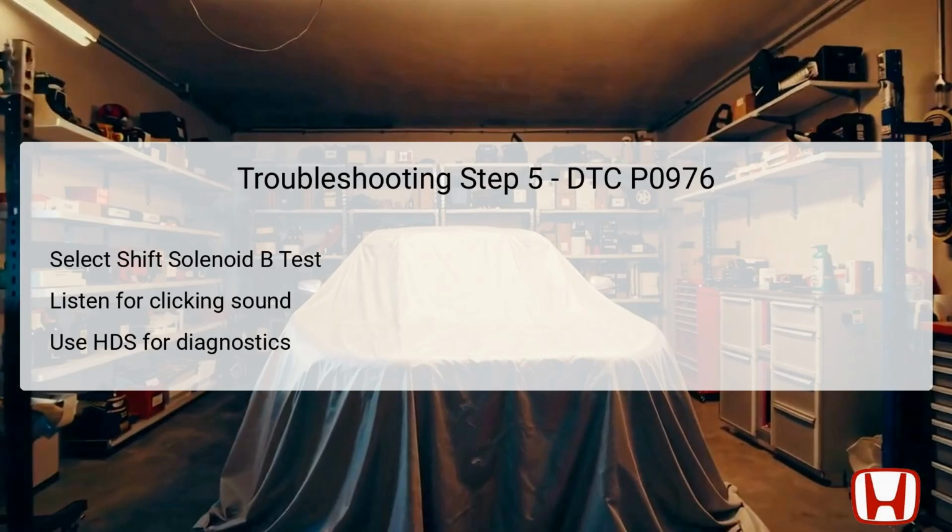If a clicking sound is audible, it signifies that the solenoid is receiving power and electromechanical components are operating appropriately. Conversely, if no sound is heard, it suggests a problem, likely an electrical fault, preventing the solenoid from activating, and necessitates progression to Step 8 for further diagnostics.